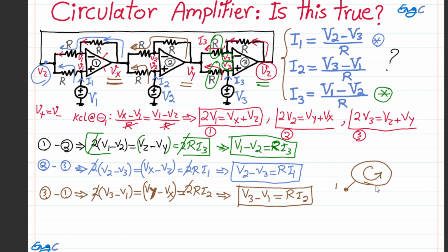So if I have port 1 here, port 2 here, as shown, and port 3 here, I'm going to show you that if I apply V1 at port 1, and connect a capacitor C between ports 1 and 2, and then do not apply any voltage at port 2, then if I just try to see what impedance I observe between port 3 and 1, assuming inside this circle I have the circuit shown, what is measured between ports 1 and 3 behaves as if you have a floating inductor between port 3 and port 1. And that's very interesting.